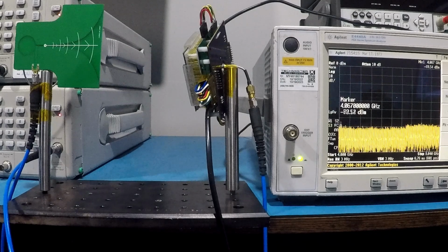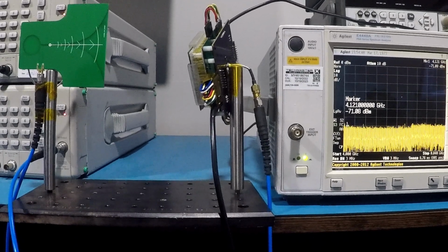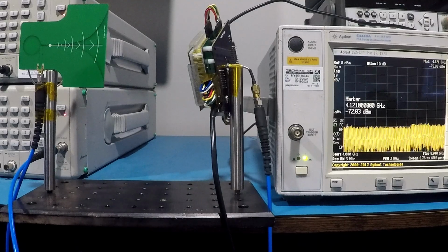I had the VNA turned down because we've got to pack it up and ship it out for calibration. So it is what it is. I had to quickly go through it and solve for 5 gigahertz, 6.4, and 7.8, the same 3 bands we had to solve for in multi-band operation, as single bands. So let's go ahead and get this all powered on and running, and we'll do some tests with it.